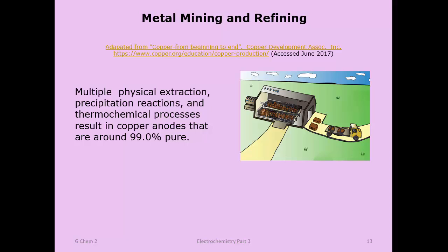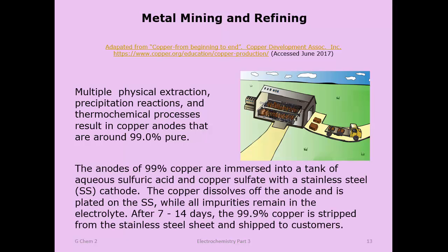So there's one more step that will actually bring that to completion, and that is those copper anodes are dropped in a copper sulfate plating bath. You just run that reaction and then basically transfer that, as we showed you earlier, in the plating bath, and you come out with 99.9% pure copper. So long story short, many of the metals, some of them are made purely that way, especially when you need to get them to a certain high purity. The last step is done with electrolysis.